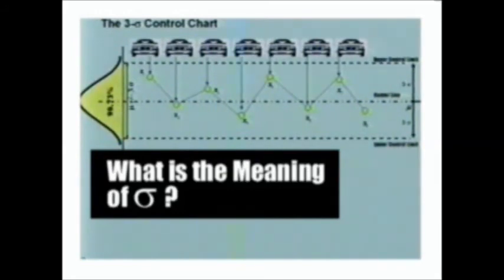If all we can do is one component or one individual observation, then the sigma that we use to establish the control limits will have to come from somewhere, which in this case will be the population standard deviation. One would ask, how are we going to know the population standard deviation?